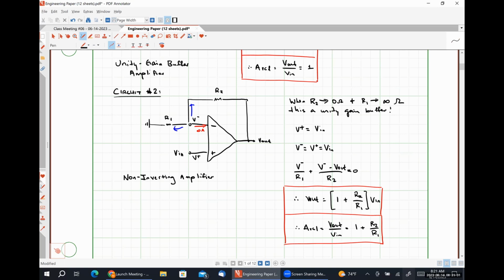And it's used really in any situation where we want to ensure that we have a positive voltage gain, or we want to effectively form a resistor biased unity gain buffer, right? So the voltage gain for this particular amplifier can literally only be 1 or larger. So it can make a copy of our input signal, or it can make a larger copy of our input signal, but it cannot attenuate signals, it cannot invert signals or make them negative or anything like that. It's just capable of providing a voltage gain of greater than or equal to 1.